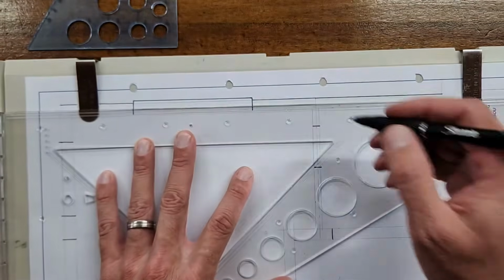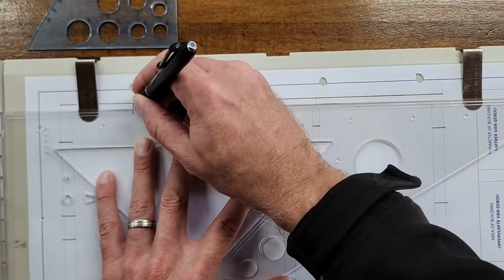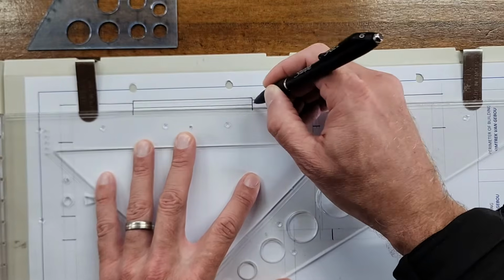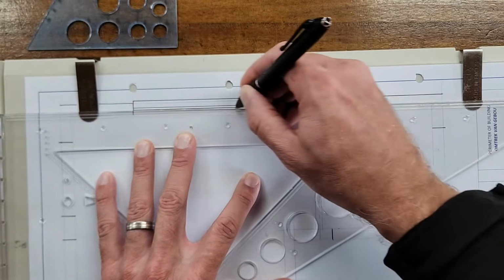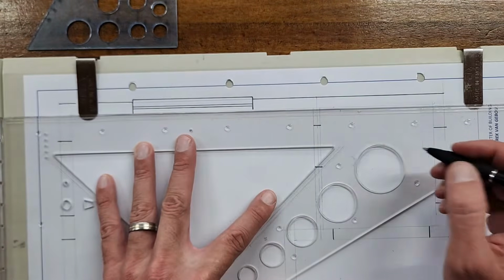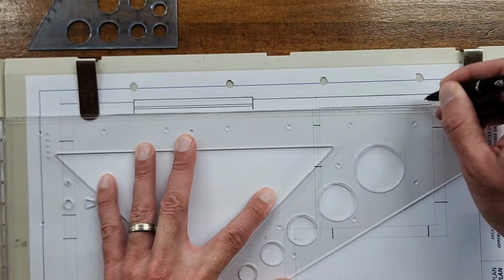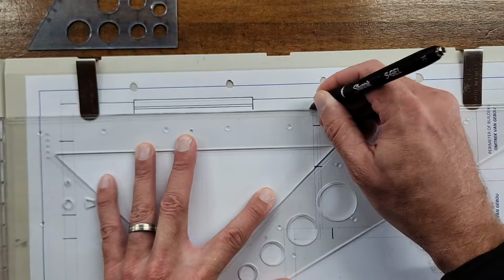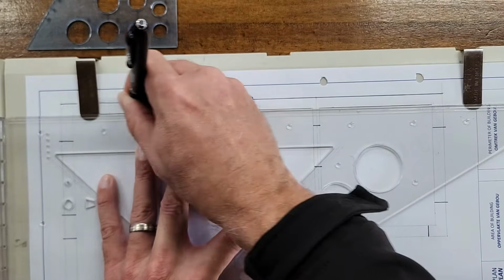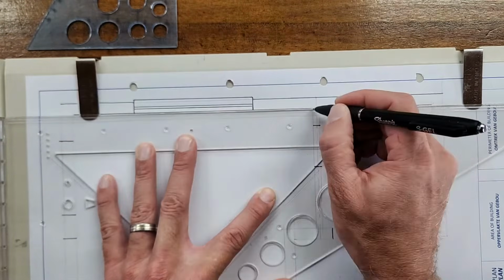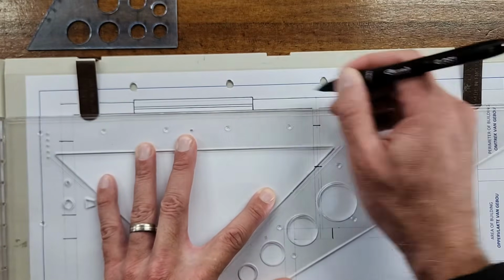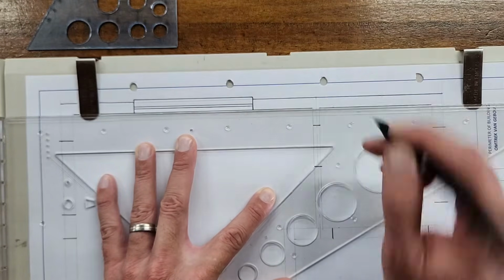Okay, then we have in the middle of the wall two center lines, or two lines that indicate the window, close to each other, in good proportion. You see the spacing there. Then please don't fill your corners, and where an internal wall and an external wall meet, again there's a gap. So we don't fill that gap in. I want a clear corner where they meet, please.